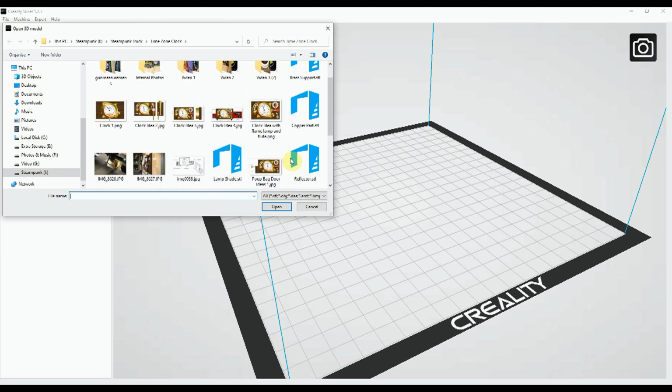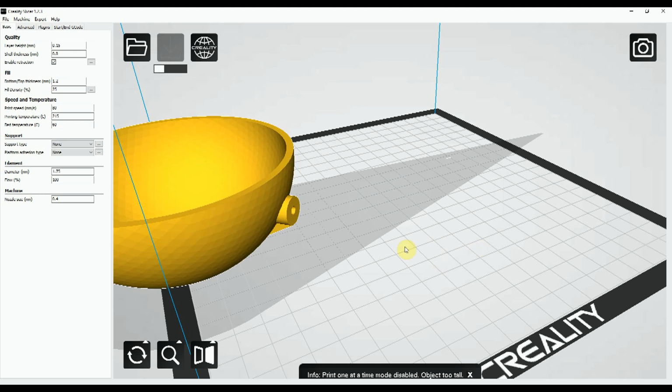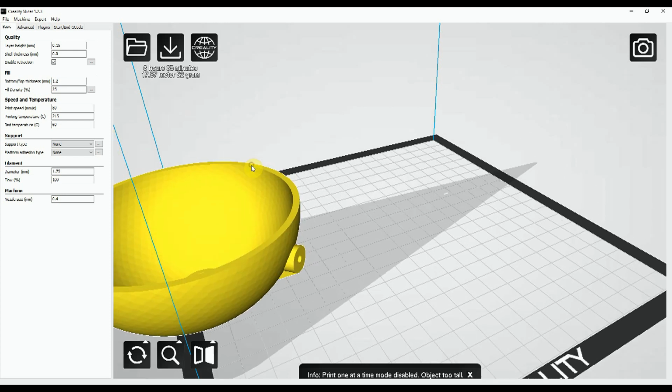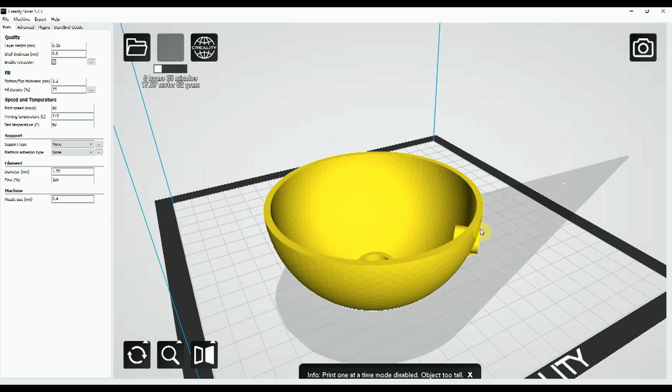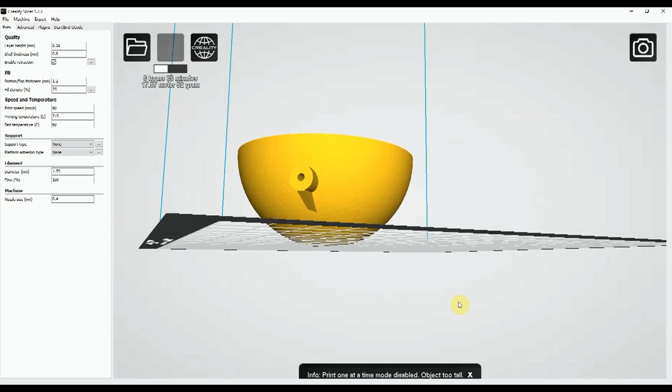So here's the Creality slicer software that comes with the 3D printer. I'm going to import the Reflector for the first file, and it will only recognise STL files, hence the fact that I exported it as that from 3D Builder. I'll move it into the middle. This is calculating currently how long it's going to take, 6.5 hours, and how many meters and the weight of the filament that you're going to require. I'll just move it back to the middle. I didn't set it to the middle in 3D Builder, so it's plonked it to one side here. Right, then it will recalculate it.